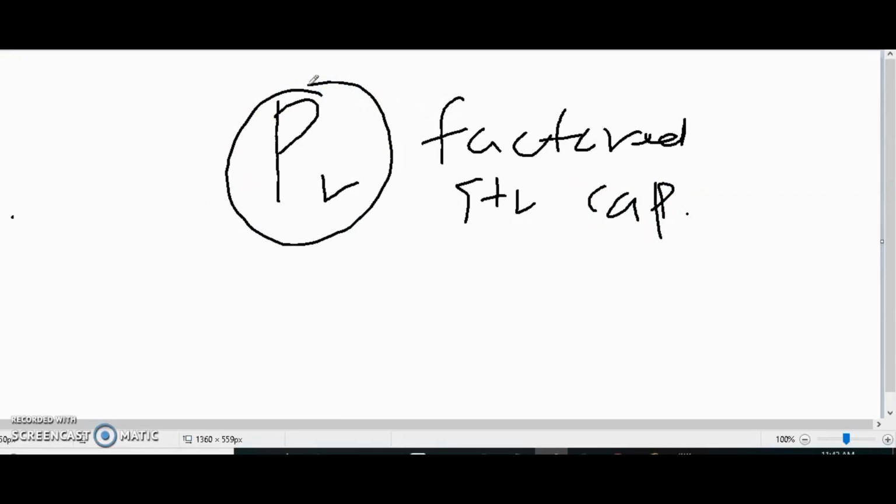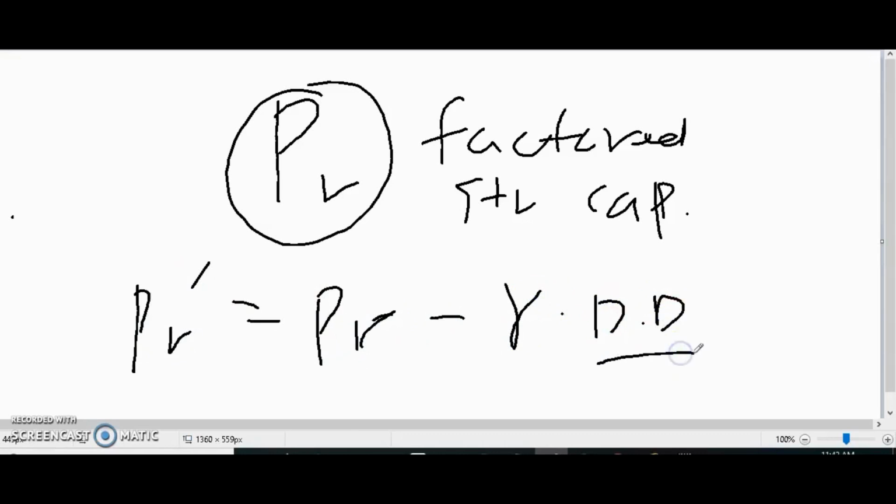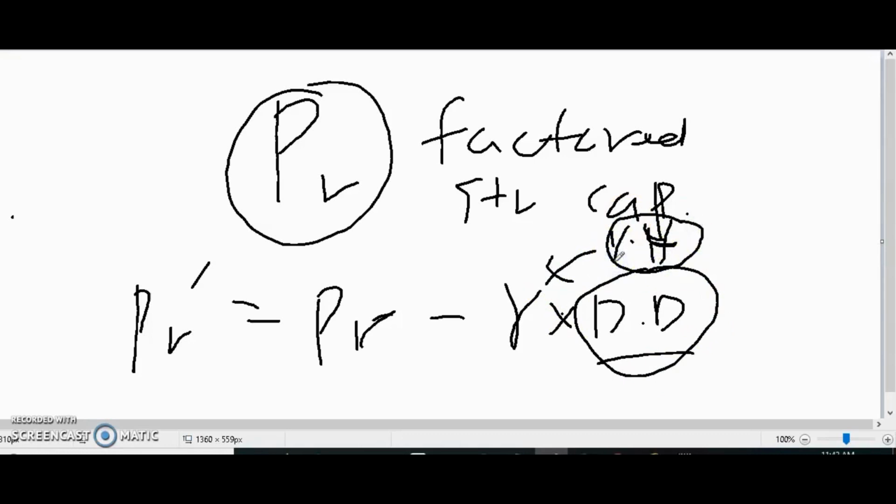Then you need to estimate the acceptable structural capacity, phi R prime. That's phi R minus the load factor multiplied by Q, which is the downdrag load. In the previous figure I explained the downdrag load: you take the negative skin friction at the upper part and multiply by 1.4, the usual load factor. So this is a load, not a resistance.